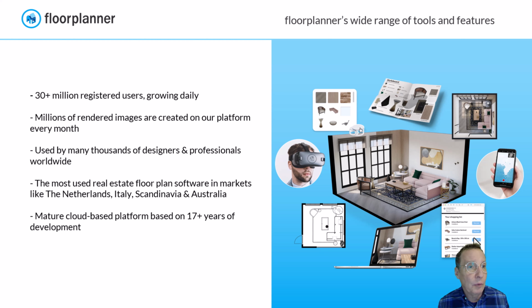Floorscanner is a free app. You can download that to your devices. When you log into your Floorscanner app, you will log in with your Floor Planner ID and your Floor Planner password. That way you'll be syncing your Floor Planner account with your Floorscanner. And what will occur with your Floorscanner, go out to the field to your client's rooms on site and take your device with you, open up your app, and you literally just scan the room with your device, much like taking a video of the room,